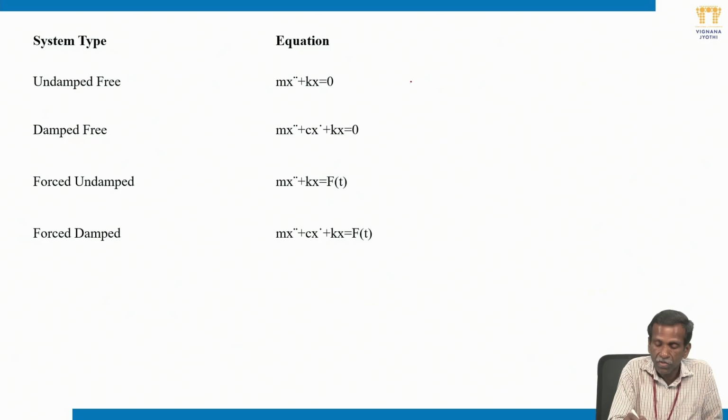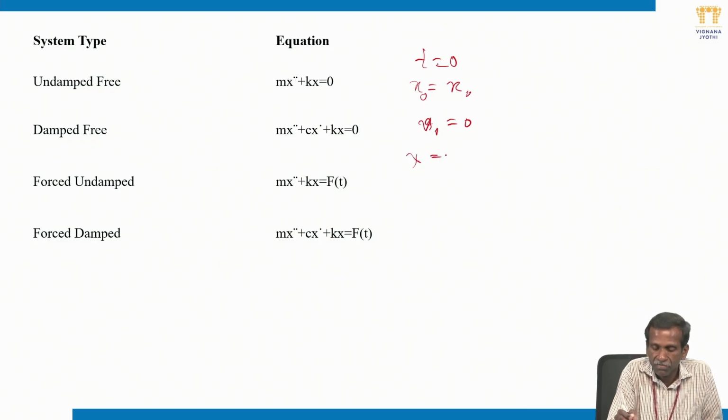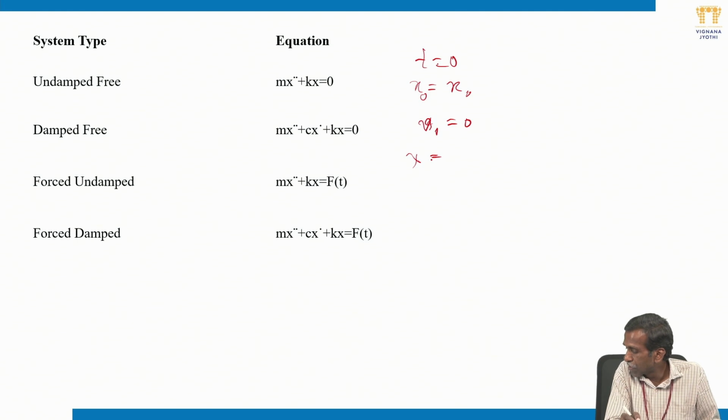Also, you can take initial conditions differently. You disturb with initial displacement x naught, and at time t equal to 0 you just leave it, so the initial velocity is 0. Then use these values in the same equation, take the derivative of the general displacement equation, substitute the initial conditions with v equal to 0 initially, and simplify. You are going to get a similar expression. The amplitude is always the same. You can verify and do that also.